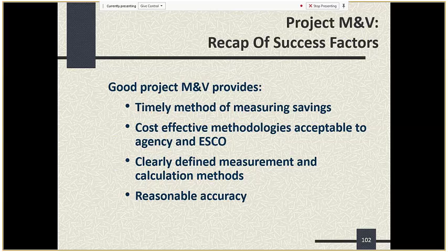So my understanding is that chilled water valves and actuators are new, and they're new VFDs for the renovated central plant because you found that a lot of the chilled water control valves were non-functional. That's correct, right? Yes, just a little added information is that most of the control valves were three-way valves.